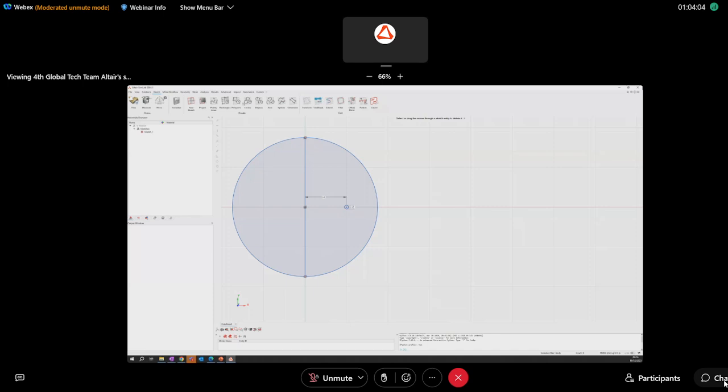Here, each time that you select one tool, you can see a tip here. So select or drag the mouse through a sketch entities to delete it. And you can enlarge the view. You have also some help dedicated to each tool. But you will see that SimLab, the Sketcher and SimLab in general is very easy to use. So to delete this part, we can just click on this line with the trim tool and the geometry is ready.